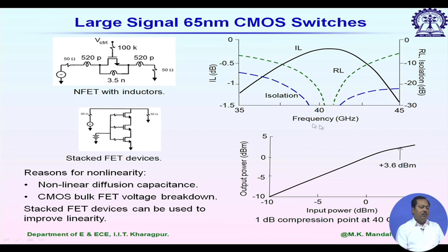Now, one problem with FET or CMOS switches is that whenever we use them, we consider only the small signal equivalent circuit and switching between the cutoff state and linear region. But say one FET switch is already in the cutoff region and we expect the switch to be off, if the applied electromagnetic signal magnitude is so high, sometimes it can turn on the FET. So, we can't use it for very high power applications. This is a limitation for FET switches.